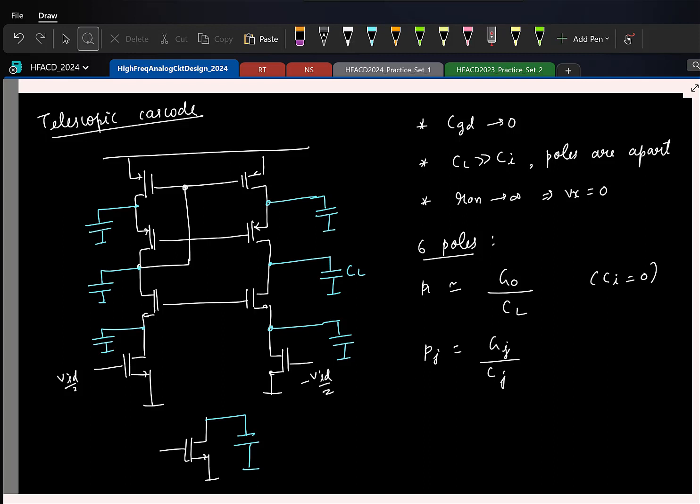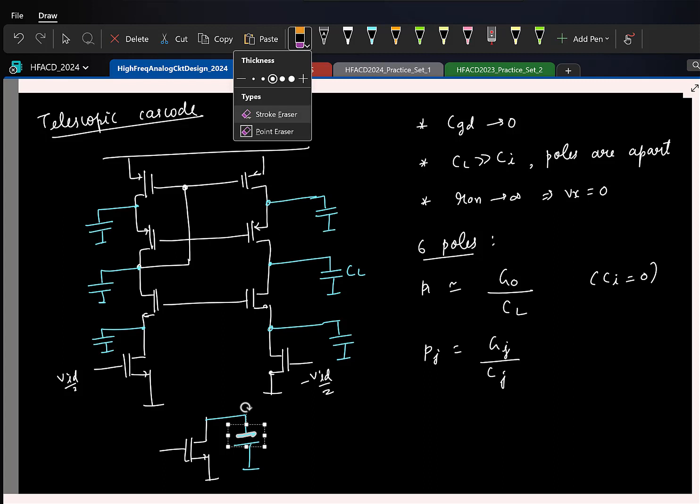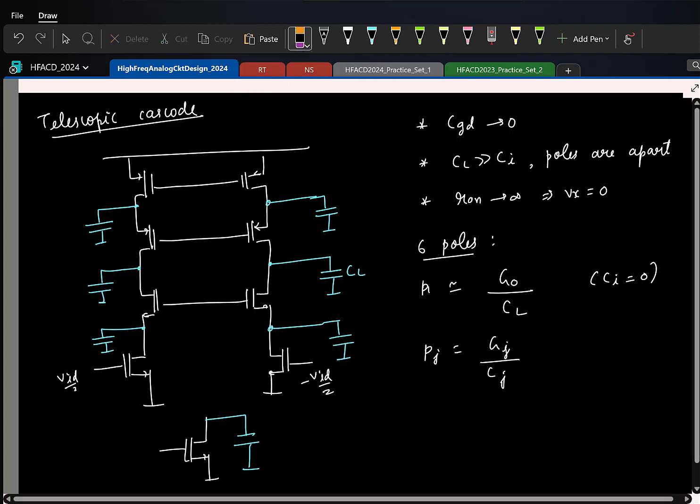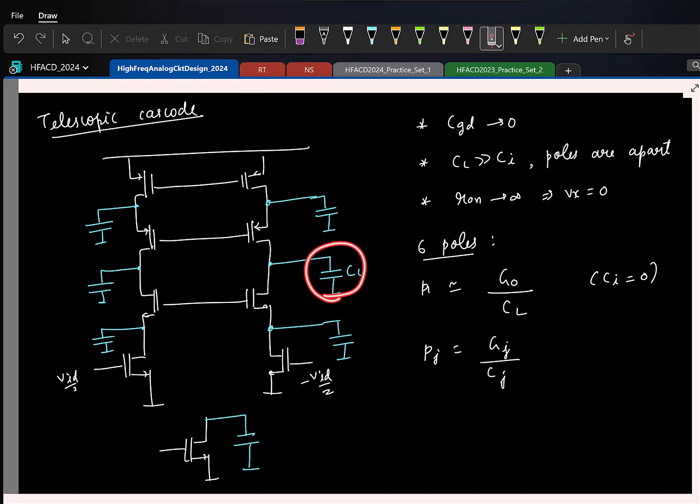Sorry? So that CL parallel to that, the same voltage will be there. I didn't understand. Voltage will be the same, CL and... No, that's what we assume. Okay, see, that symmetry argument, the idea was it is kind of symmetric except this connection, right? But right now, even if you don't have this connection, the circuit will not be symmetric, right? Because the capacitance can be different. The CL is the output load you have, here this is the parasitic capacitor. So they need not be equal, I mean they won't be.